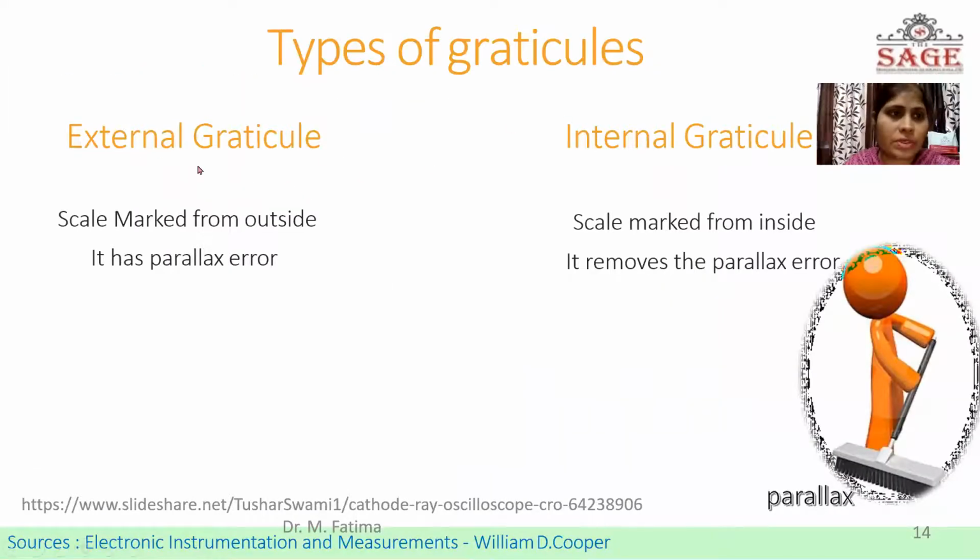Types of the graticules: external graticule and internal graticule. The scale marked from outside is called external graticule, and it removes the parallax error. And the scale marked from inside of the screen is called internal graticule. The internal graticule also removes the parallax error.